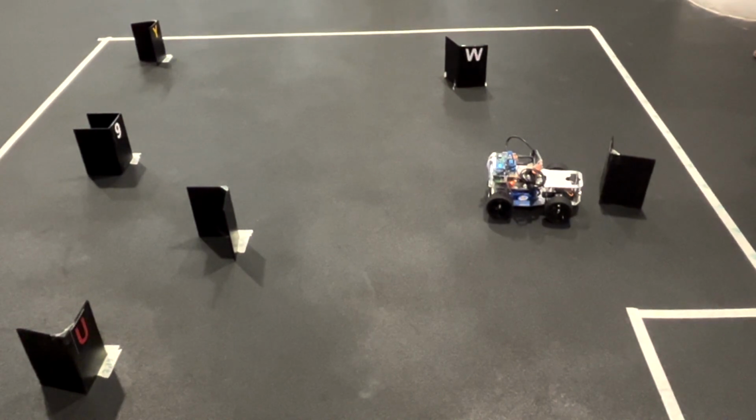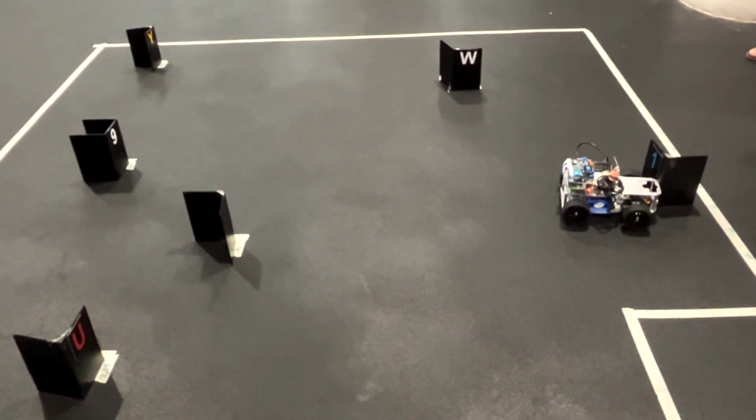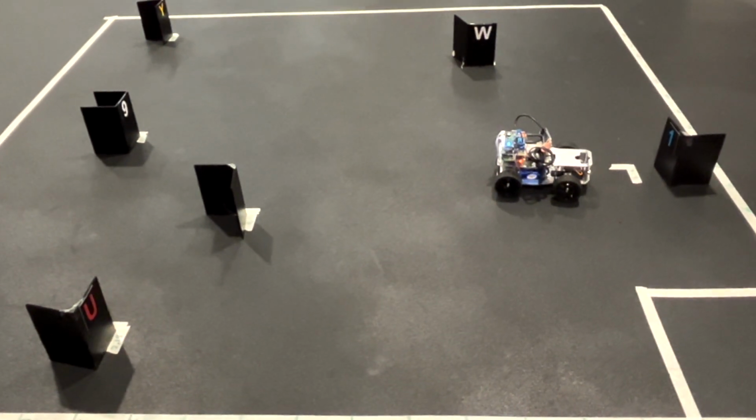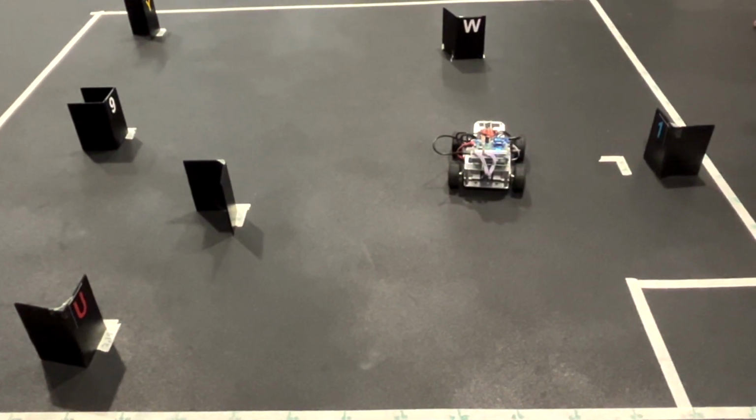For the run, we implemented a protocol in case no image is detected. During the protocol, the robot will move forward 1 block, do a scan, move backward 2 blocks, and then do another scan. It will stop and find the next path after the protocol is done or detected an image.